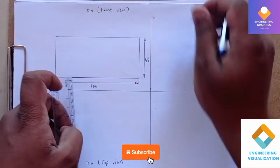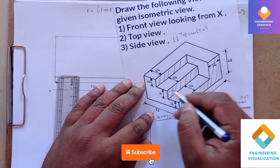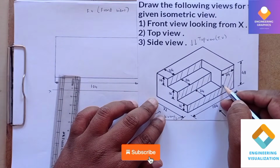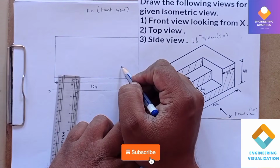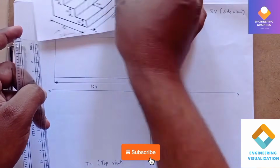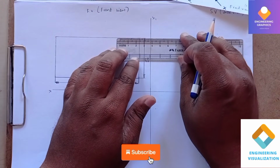Okay, so now you analyze the diagram. In the diagram you can see the L type shape component we should get, and it has a height of say 16, and from there it has a dimension of say 24. So we can mark here 24, and then 16, like that we can do. First I will be marking for 24 mm, and then vertically downward I will draw a line. So mark for 24,